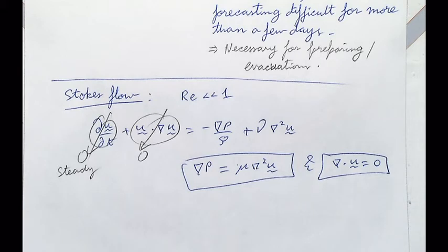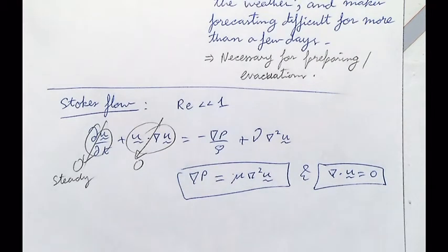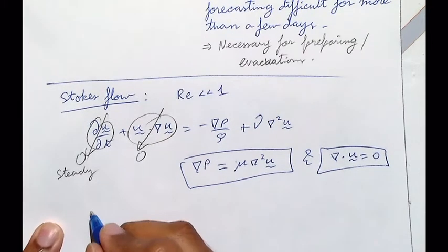In turbulent flow, you cannot do this. That's the point, okay? In turbulent flow, if I say at 1 second the flow field looks like this, what will happen at 2 seconds later, can you give me exactly the answer? You cannot. You have to go slowly, you have to simulate, okay? And another thing is in Stokes flow, if you redo the experiment 10 times, you will get the exact same thing. In turbulent flows, you are guaranteed to not get the same exact thing. If you repeat the same experiment, the flow will look completely different. Make sense? Yes. Okay. So, this is time reversal.